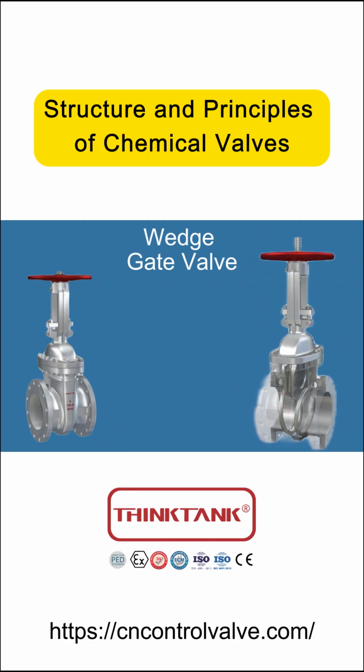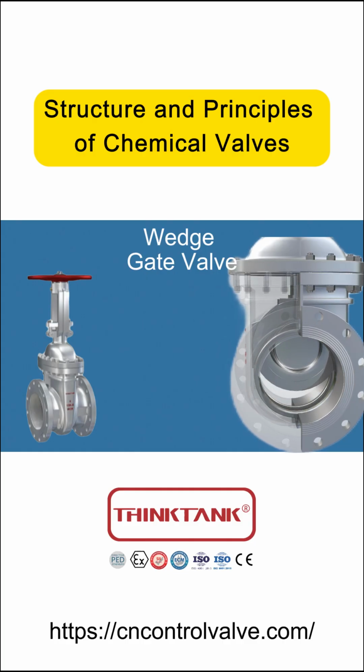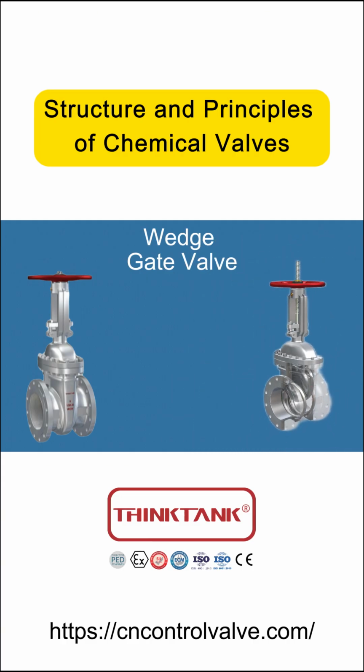A wedge gate valve. The sealing principle of a wedge gate valve relies on the combination of the wedge-shaped gate and the sealing surfaces on the valve body to achieve a seal. The sealing pressure comes from the media and the downward pressure on the gate. Because the gate of a wedge gate valve has a slope, the sealing surfaces can separate more quickly during the opening process, resulting in less wear.